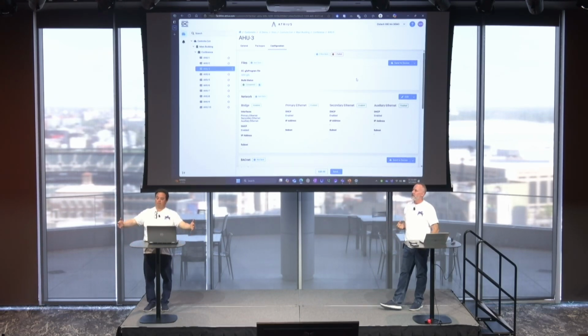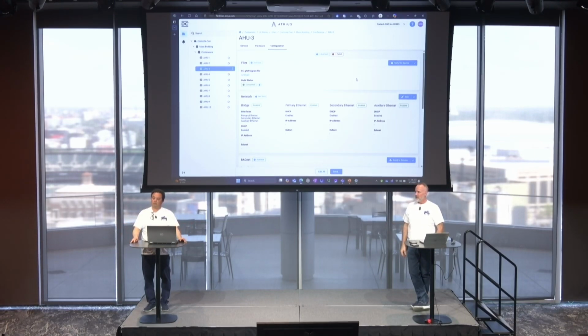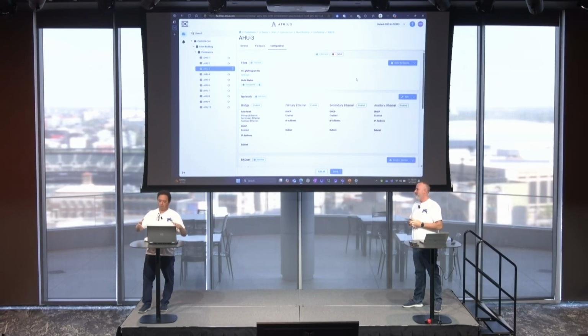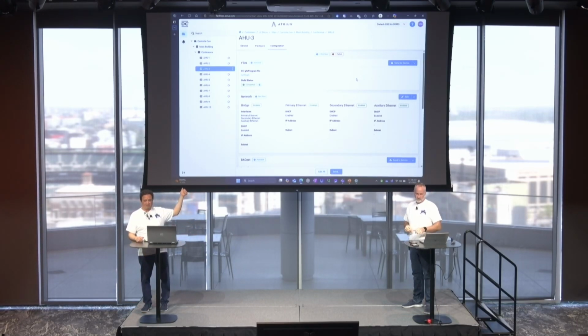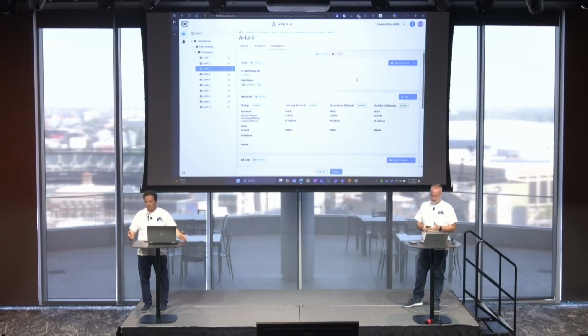That's a battle I think we have to fight moving forward as an industry, because as things get more and more IoT focused, the network in a building is going to have to be done sooner rather than at the end of a job. Some of our partners will carry a router with wireless access, and then they'll daisy chain the devices. But it's a temporary network. That's why I was saying sometimes setting up the IP up front is not the best way to go, because you don't have the final information from IT. No, that's perfect. That's exactly what I was hoping your answer would be.